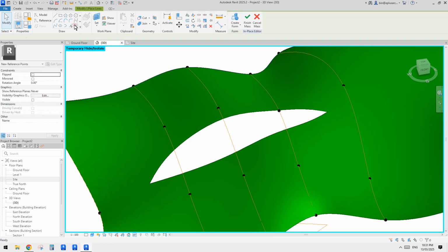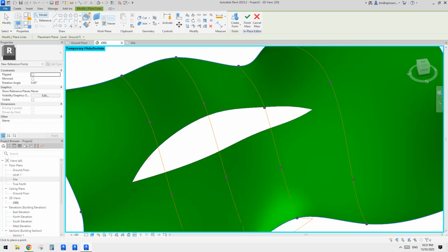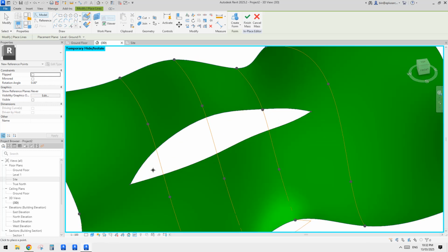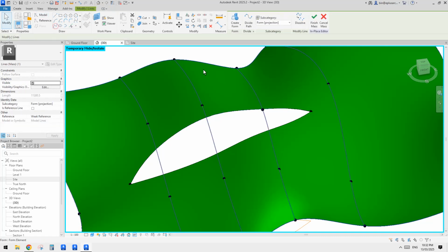Now I'm going to place a point, use draw on face first, and then I'll move this one. Onto this edge, I'll type SE to snap to the endpoint, so it will place onto the endpoint of that shape. And do it again, SE, tab. So we have another point. Now we can select this point and create a spline through points.